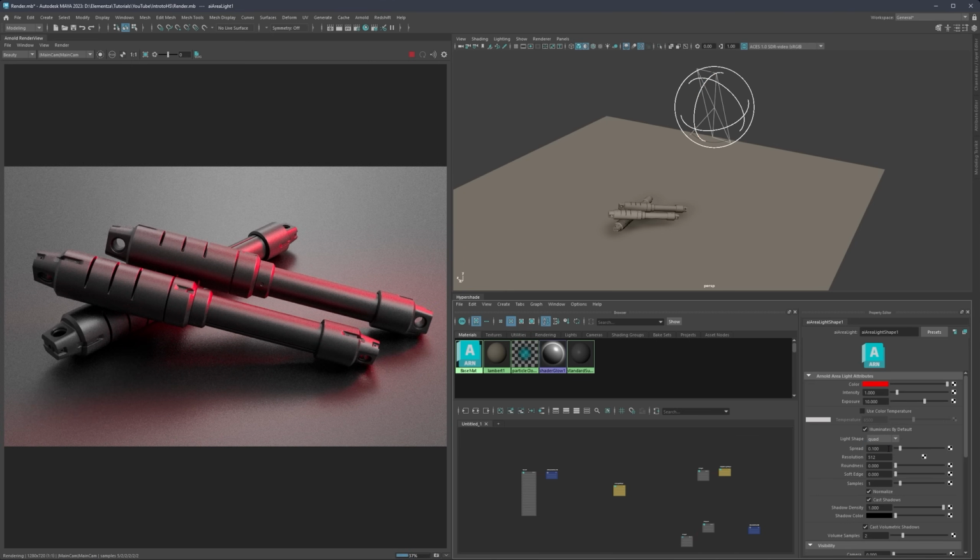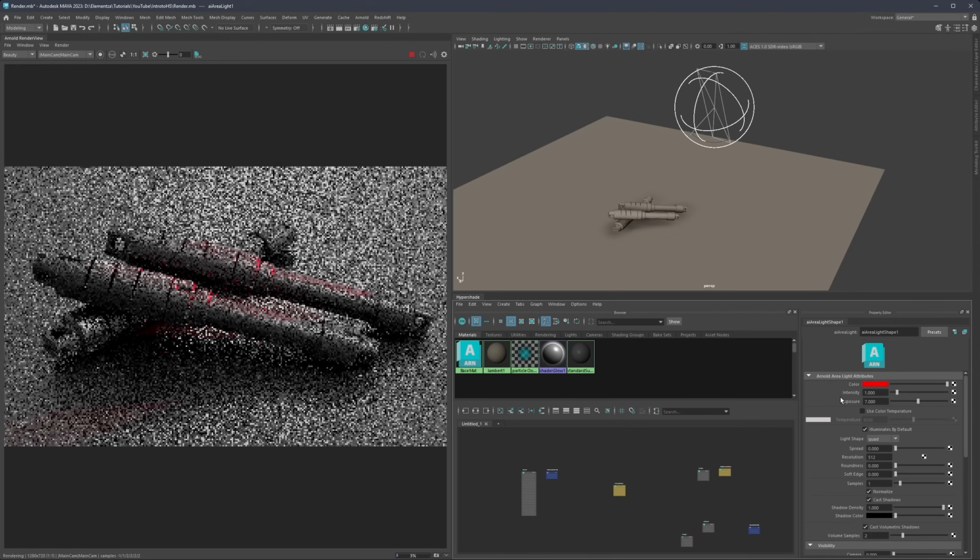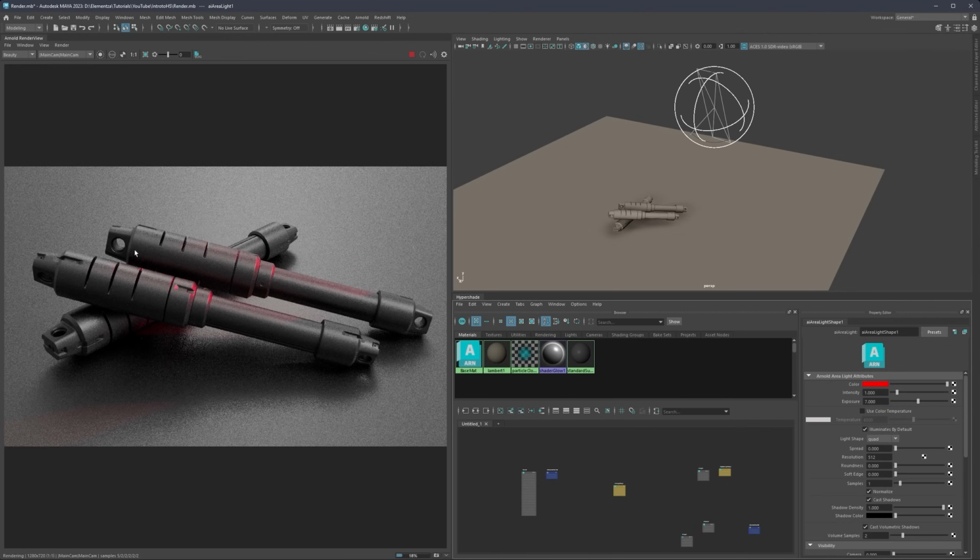Or let's say if we release the spread all the way to 0, maybe we can tone down the exposure to something like 6. And now we're going to get a much more subtle tone on our objects. And maybe, let's say, increase it to 7. And now we have a clear visual representation of where this light is actually hitting. And this is kind of that quick setup.